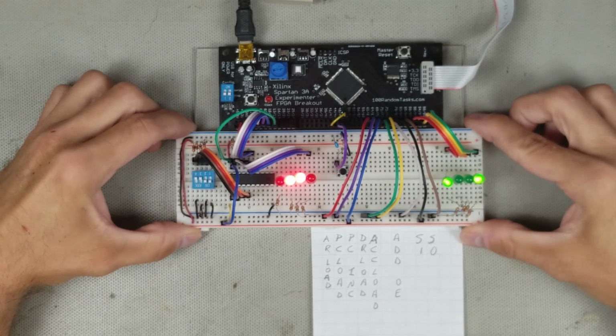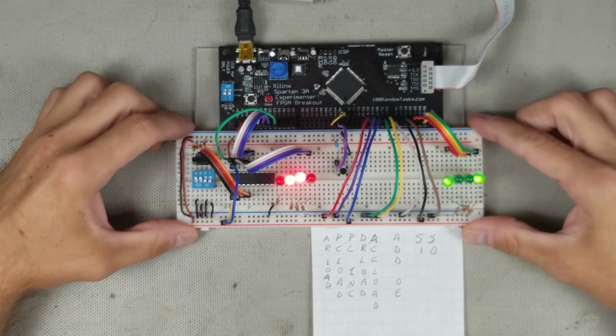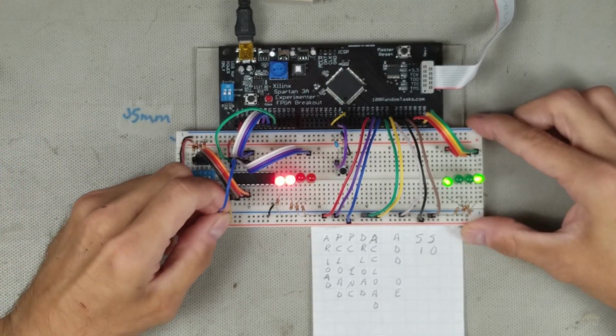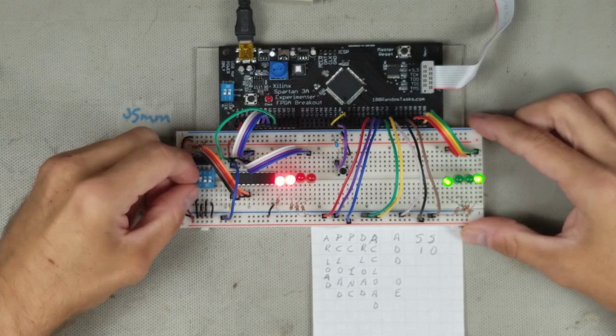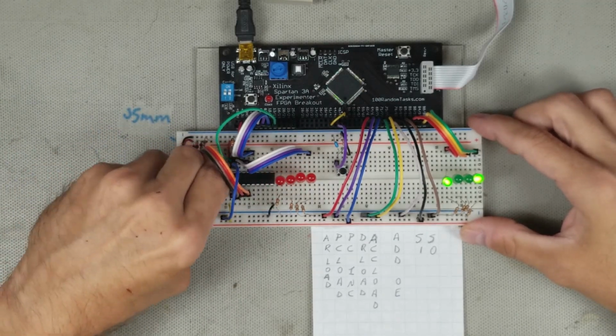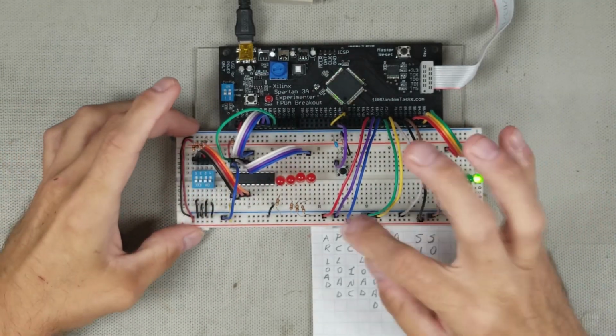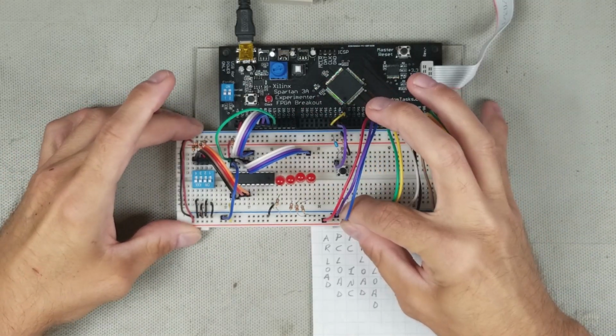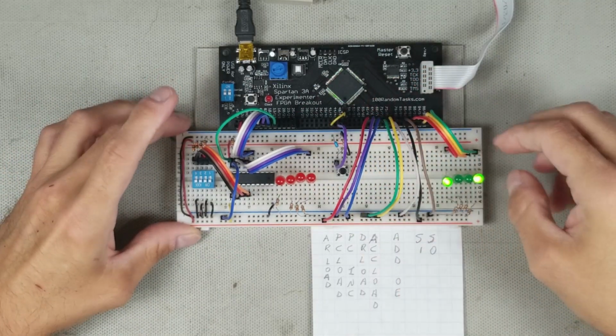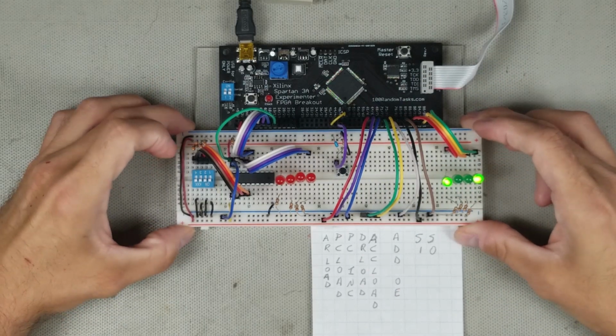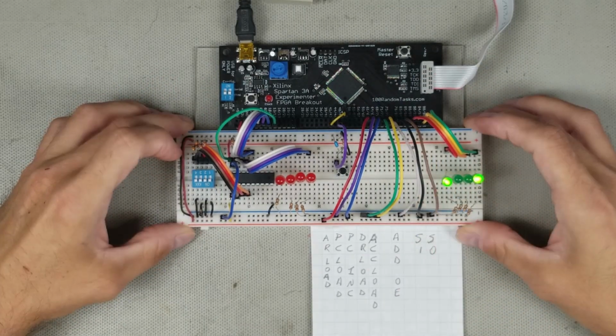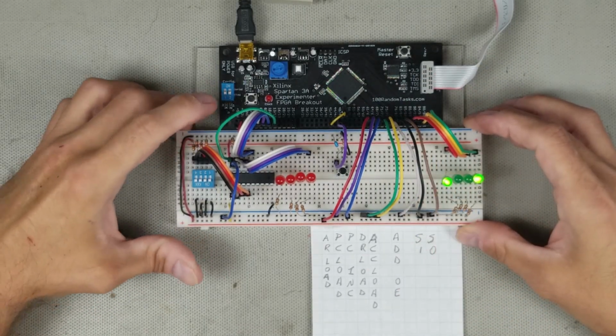Lastly, let's pass each register value to the address register. I'll set the read-write to 0 and set the dip switches to 0. Set the AR load and all others to 0. The select lines being 0, 0, select the accumulator. Now we'll cycle the clock.